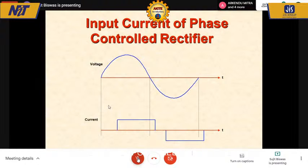Higher power, it remains because there is no, shall I say, economically viable, competitive replacement as of today. Technologically, yes, but it has to be economically viable. So it still dominates with a lot of adjustments. So the phase control rectifier is definitely a good example of something that creates both harmonic problems and VAR, and you can definitely distinguish and separate out the two.